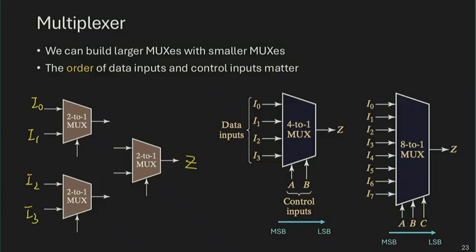What do I do? Well, I can connect them together so that everything goes into a single output. And now I need to put down the appropriate selection signal. I want AB equals 1, 1, for example, to select I3. That is my goal. I want an input of 1, 0 to select I2.